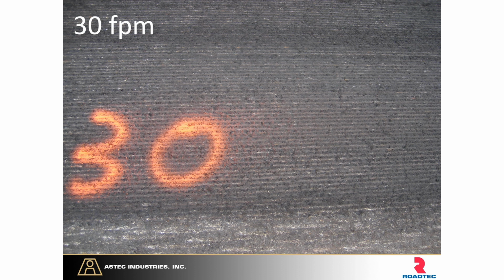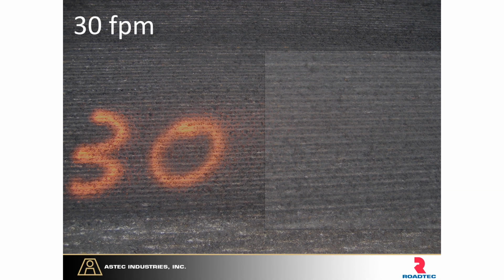Now what we've come to accept as more of a standard milled surface is really incorrect. You start to see a V pattern once we hit a certain speed. We call it a chevron pattern a lot of times, and that means the machine is outrunning the drum. Our forward propel speed of the machine is faster than the drum can remove this residual material.